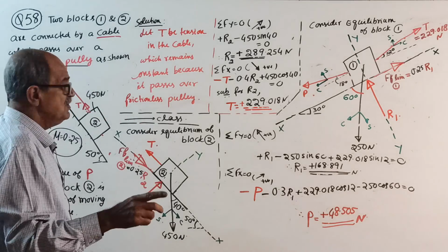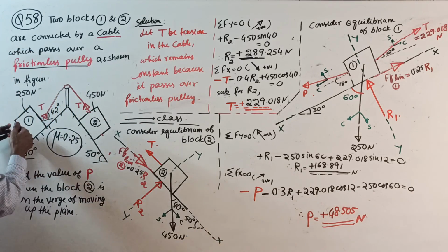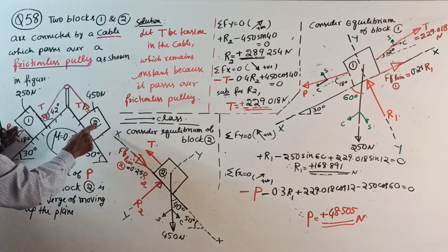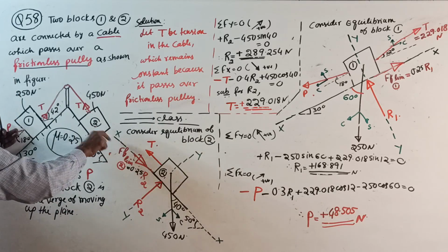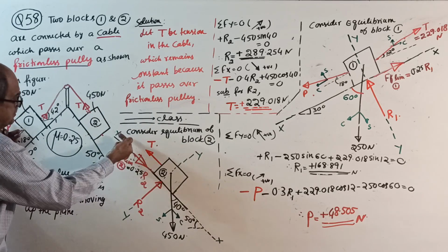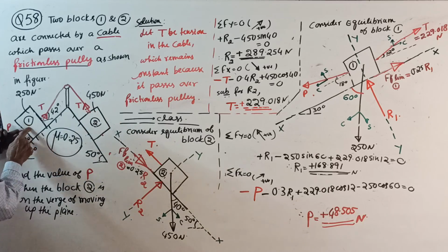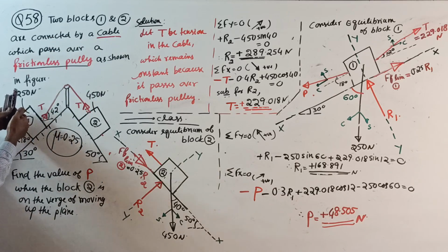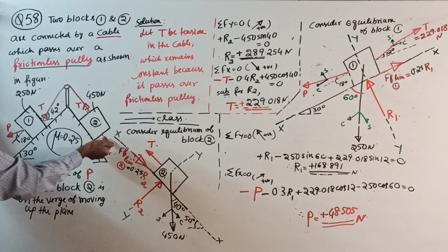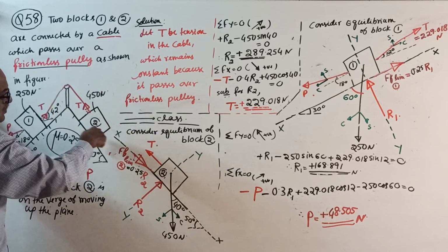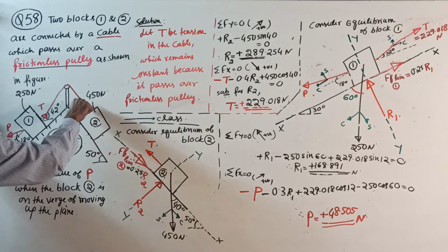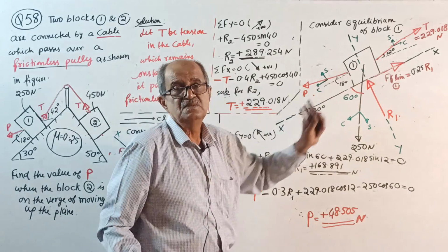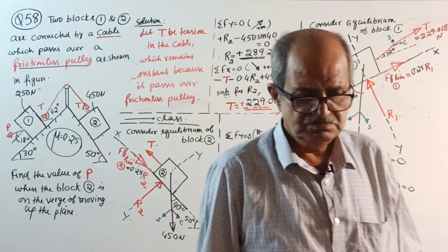And lastly, last time you applied the force P to prevent block 2 from sliding down. If you remove P, 2 will slide down. So for 2 sliding down, friction was up, and 1 moves up, where friction is down. But this time, P is such a force that block 2 will move up. When block 2 moves up, friction is down. And when block 2 is moving up, block 1 will come down, so friction is up. Over. Now I will change the numericals and continue.